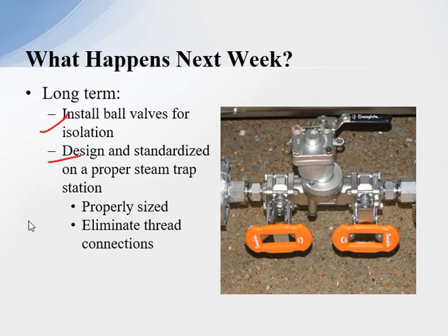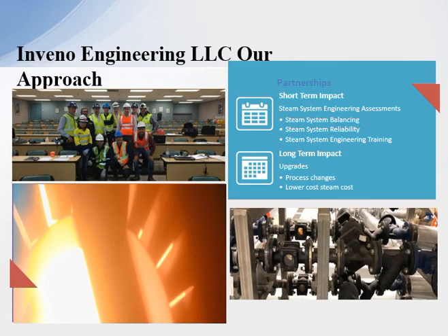Design, standardize on a proper steam trap station. This happens to be a steam trap station using tubing, tube connectors, ball valves for isolation. Back here is the blow-off valve for the strainer that's built internally, and the steam trap located. A very small, compact package, and eliminates threaded connections. Just one of many steam trap station designs.